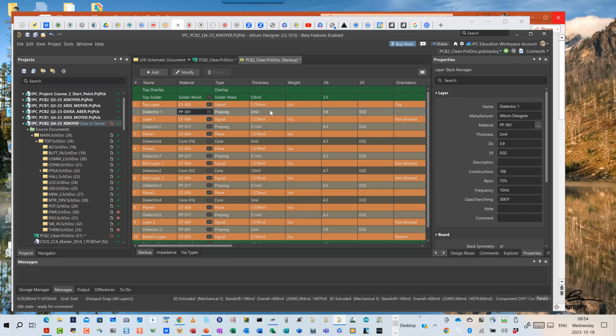So with few exceptions, we absolutely want the foil construction where the outermost layer is prepreg, but then the other is you just alternate a prepreg, then a core, then a prepreg, then a core, and so on. Must be done that way. That's how the manufacturing works. So we're going to get into that when we get into the manufacturing week.